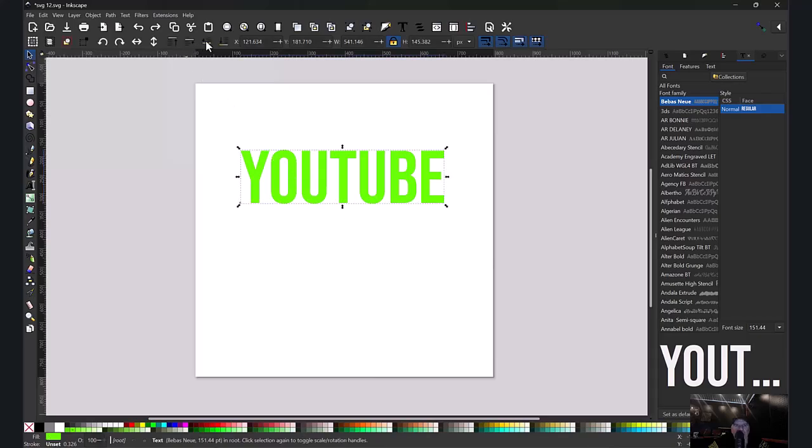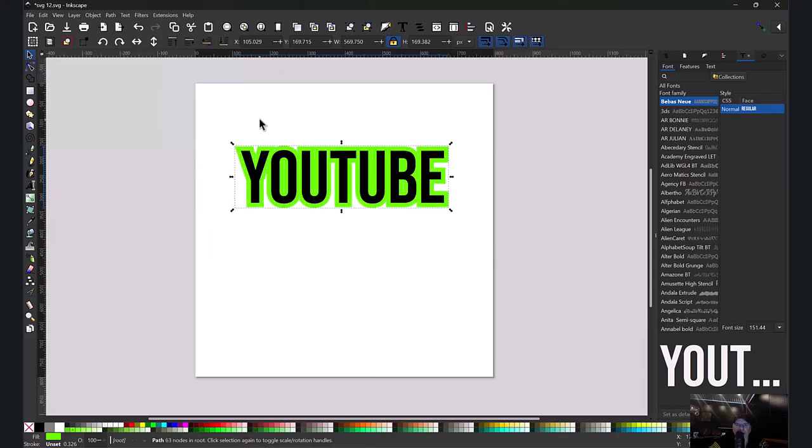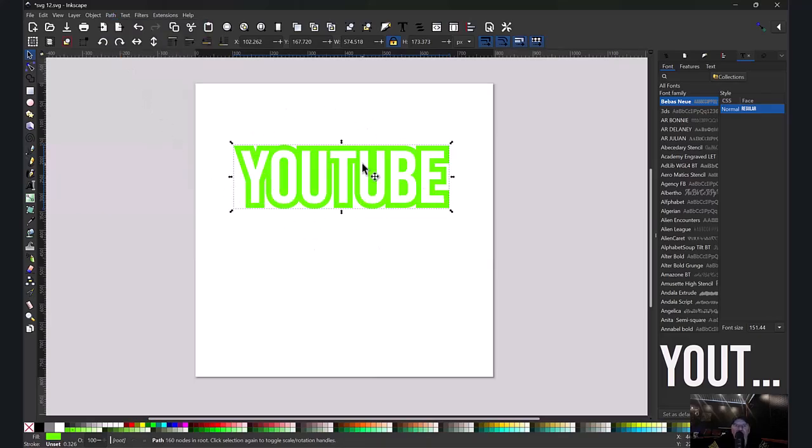So I'm going to select it and send it to the back right here. I'm going to hold Control, hit 0, and grow that. Now you see that? You can select both of these, come up here to Path, and go Difference, and now you have a hollowed out text of what you were working with before.